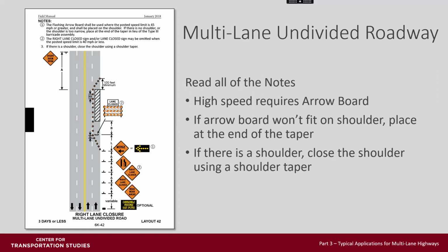If the arrow board does not fit on the shoulder, then place it at the end of the taper. And remember, if you use an arrow board on the shoulder, to include a shoulder closure taper.